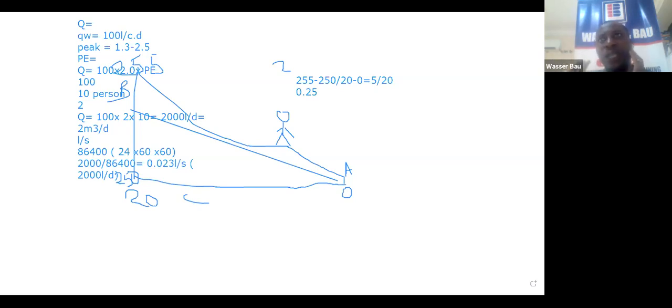In design we have a lower boundary, an upper boundary, and a safe boundary. Now, depending on the terrain, you might not have a choice but to go down to 2 meters or 2.5 meters. Like I said, in Europe, because of freezing and winter, they go very deep. And then maybe, to achieve a gentle slope, you might need to go too deep, but then you must consider the cost of going too deep.